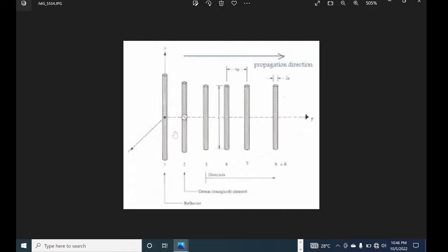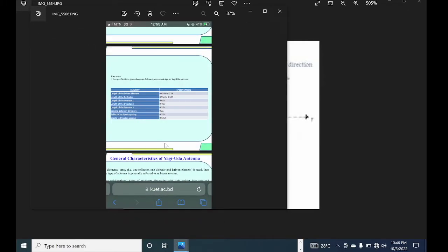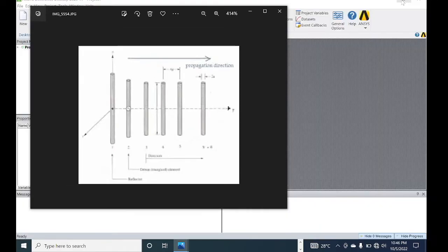By theory, the reflector should be 5% greater than the dipole, and the difference in height between these elements is usually negligible, very minimal. They don't usually differ, so the difference in their distance is small. So I have with me their dimensions.